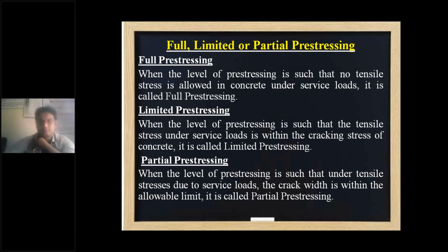Okay, so when you want to see the member under full service loads, then you can go for full pre-stressing. Within the cracking stress, if you want to do, you can go for limited pre-stressing. So you have to decide the mode of stressing and the magnitude of stressing for the particular element. Full, limited, or partial. So that is how the three modes of stressing are defined.